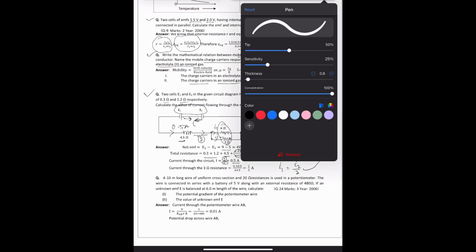Alright, let's do it. You have to do it. Okay. So 0.5 equal to I1 plus I2, I1 is I2 by 2 plus I2. So it is 3 I2 by 2. 0.5 is equal to 3 I2 by 2. So 2 into 0.5 means 1. 1 by 3 is equal to I2.